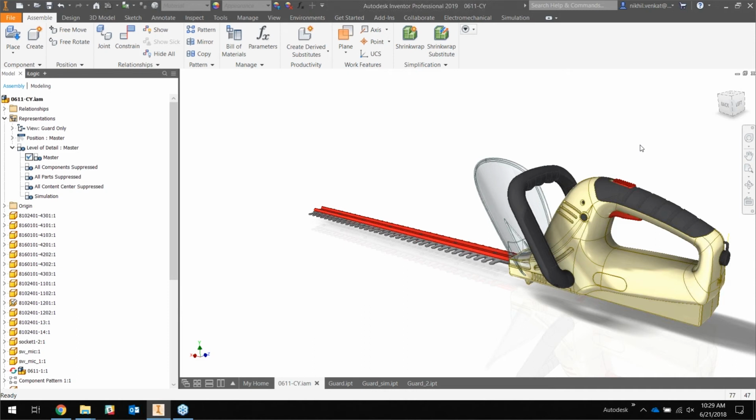All right. Jerry is asking if there's any disadvantage to just always running nonlinear instead of linear. The only thing I can think of is time, because nonlinear will take a little bit longer. Anything else you'd like to add to that, Nikhil? And complexity as well. Nonlinear does add a ton of complexity to the problem itself. So even if you do have contacts, there may be times when it's just easier to approximate those contacts as a linear problem.